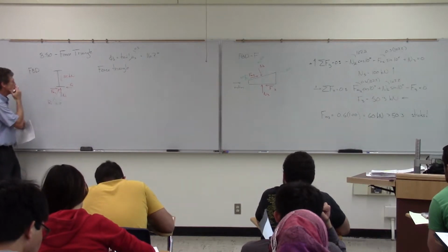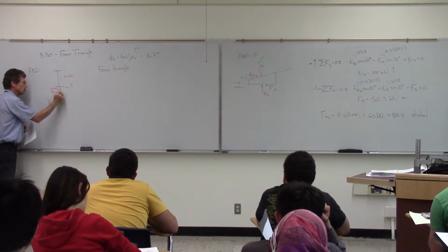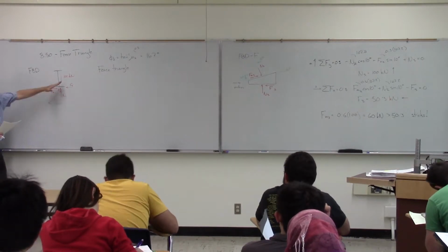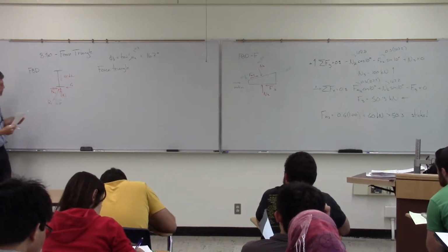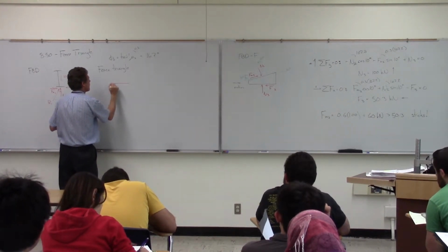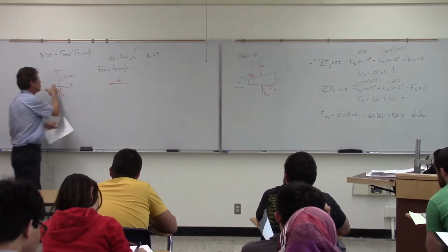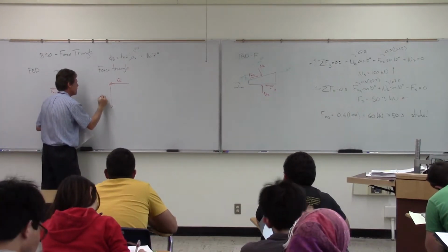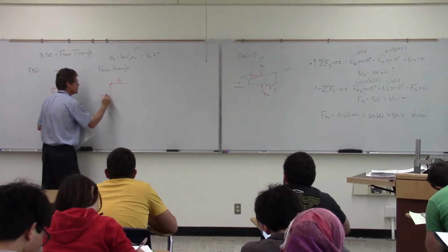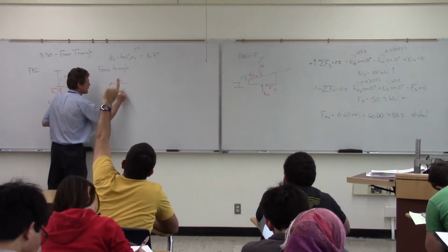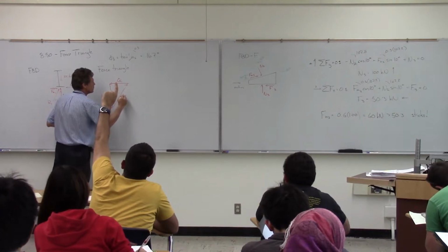So again, what we've done now is we've combined our friction force into a single resultant force there. We're now down to a three-force system. So we've got Q, which is a known direction. We have 100 kilonewtons, which is another known direction. And then finally, our R has to get us back to 0.0 for equilibrium.